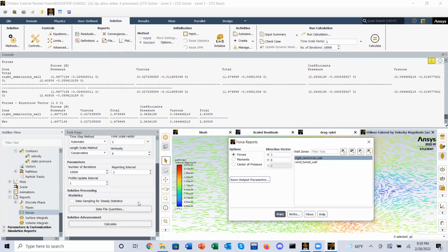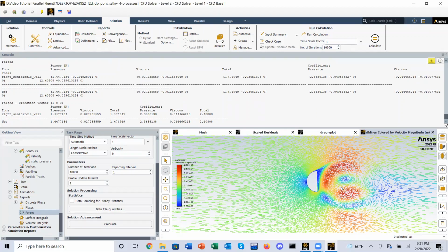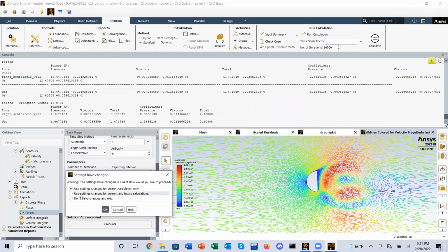You can also do that earlier. If you write it to a file earlier, then as you run it, it'll save every iteration. And so you can see the final value of the drag force after it converges. That's the more proper way to do it rather than print it out. So you want to see the last value that was pulled. But yeah, that should basically be it for the project.